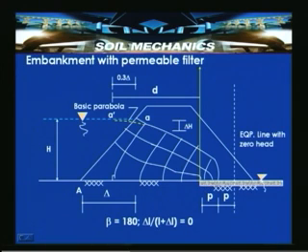When this qualifies as an equipotential line, this will be the upper phreatic surface, that is the phreatic line, where the phreatic line meets this equipotential line with zero head orthogonally. These are approximately shown at right angles. Here the second flow line meets this point orthogonally, and again here, which is approximately shown, it meets orthogonally.